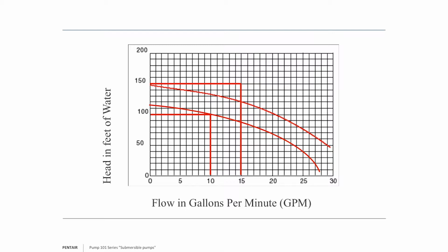But if they would have used a variable frequency drive, they could adjust the speed, which adjusts the head and adjusts the gallons per minute, and they could achieve that. And so the pump with the full-sized impeller would grow with their needs. Once we cut the material, we're done.